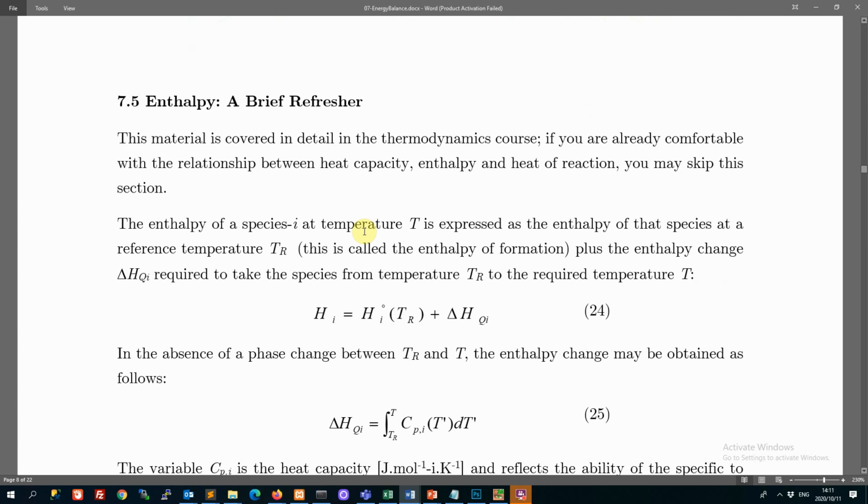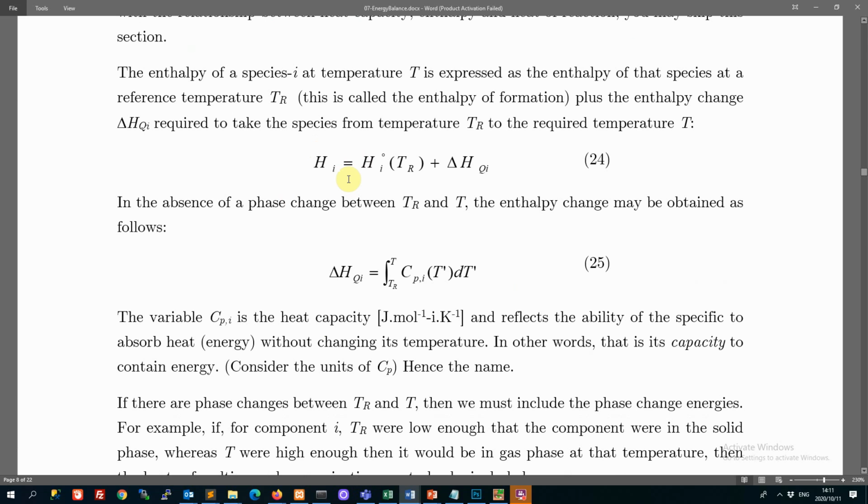Anyway, let's go on to just reminding ourselves how to calculate these HIs. I said the moment you see capital HI, you feel a bit happier. So how do you actually do that? To calculate enthalpy, normally we have the enthalpy tabulated at some reference temperature. So we are told, for hydrogen, the enthalpy at 25 degrees under this pressure is this value. So you have some reference amount, and then you'll say, yes, but I'm not at that reference temperature.